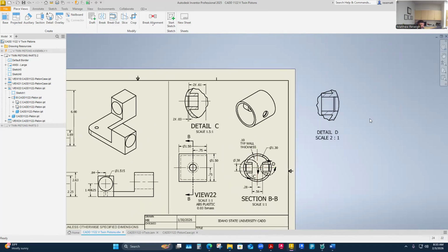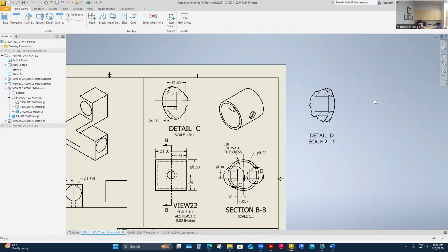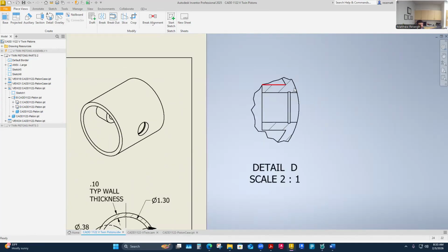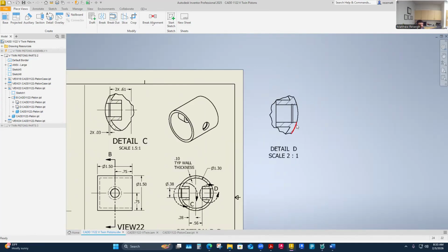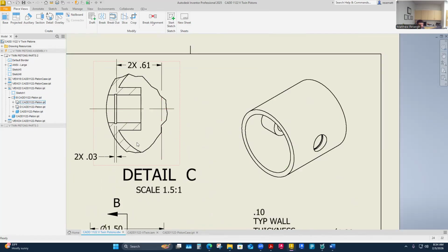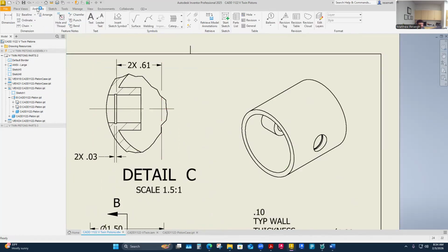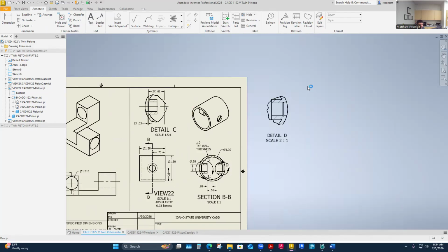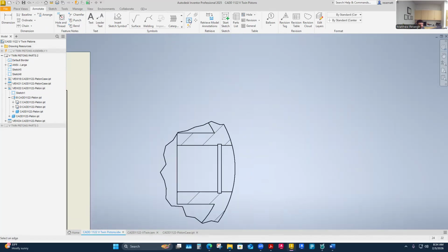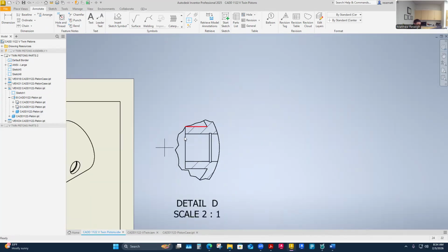And then I just jumped over here and went to town on dimensioning it out. The other thing I added was the center line. You can see that the way I'm locating these grooves is by using the center. I could pick the center mark, annotate. Here's center. I know it's buried, but I think I just picked the center mark of this bore or something. And there's the center. That's at least the center mark for it. And then I dragged it out.